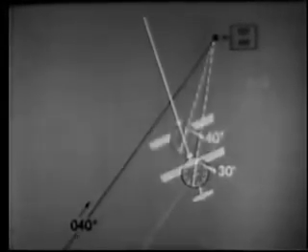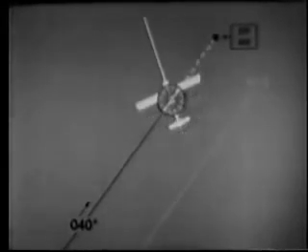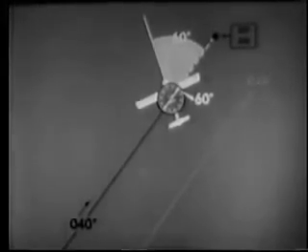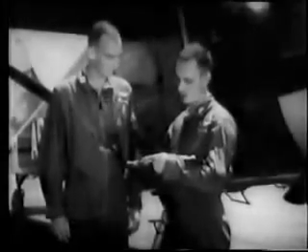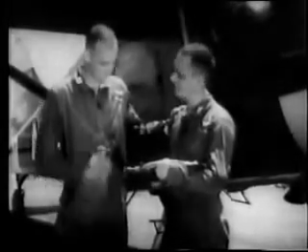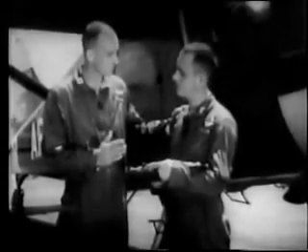Remember, too, the procedure when intercepting a specific track. You will have reached the track when the needle is deflected an angle off the nose or tail equal to your interception angle. This student feels better about ADF. When you've used the automatic direction finder in flight, you'll know that it is a valuable aid to navigation.